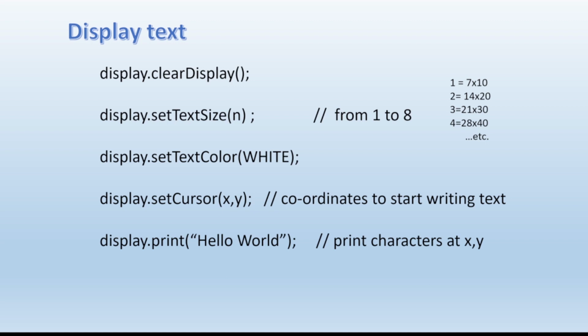All the pixels required to display Hello World. It's setting them up in the memory inside the OLED. And then once you set up in memory, you have the one final command, which is display the display. And at that point, all the contents of the screen memory inside the OLED are displayed on the screen itself.